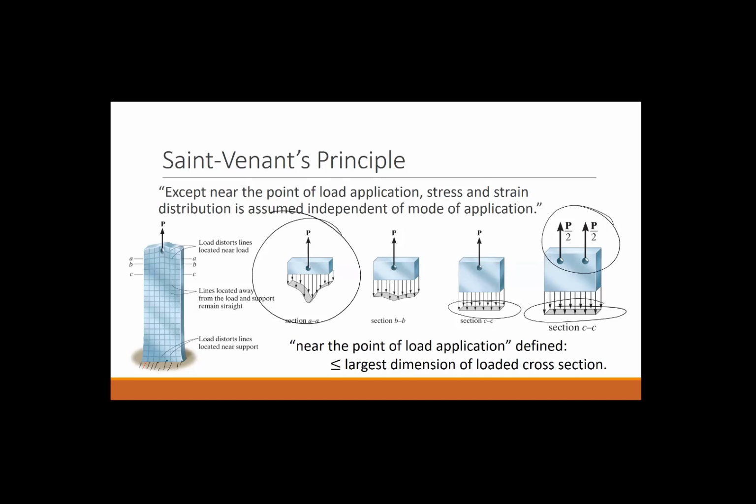Where is this object going to fail? Where the stress is greatest. And if we have a uniform stress state in the middle, and the same force has to transfer through the entire object, if we have this non-uniform stress state that sums to the same force, this magnitude must be larger than the average, correct?